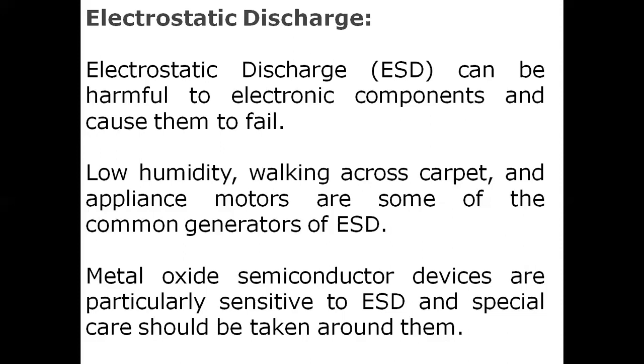Metal oxide semiconductor devices are particularly sensitive to ESD. So it may be asked what kind of devices are sensitive to electrostatic discharge. Generally, all the devices which are made of metal oxide semiconductor are sensitive to ESD. Metal oxide semiconductor devices are particularly sensitive to electrostatic discharge, and special care should be taken around them. Whenever we are handling that kind of device, we should take care about ESD. Otherwise, they can be damaged.